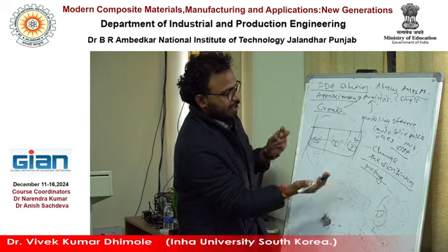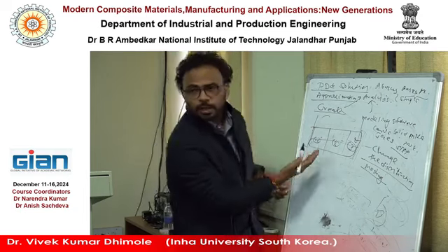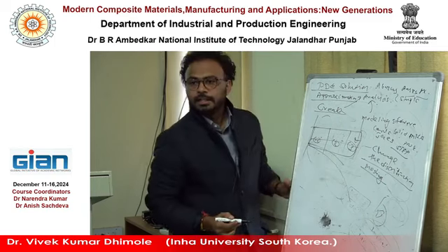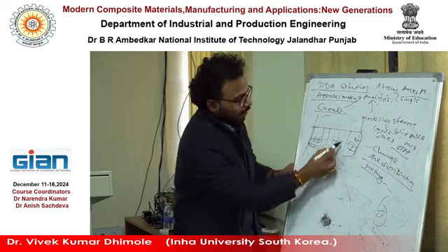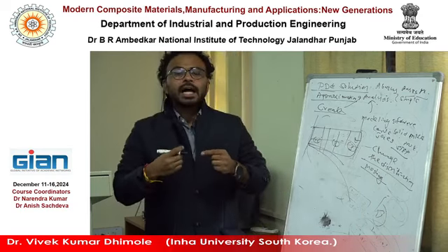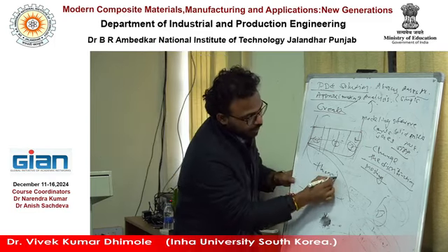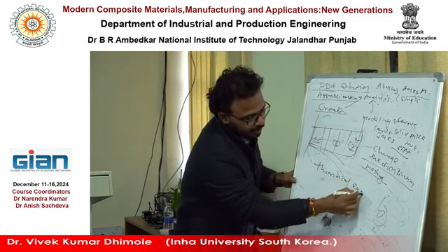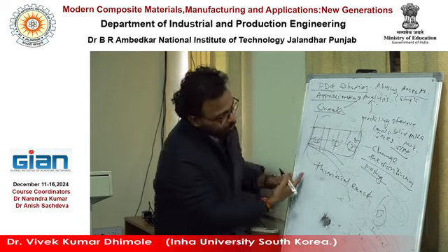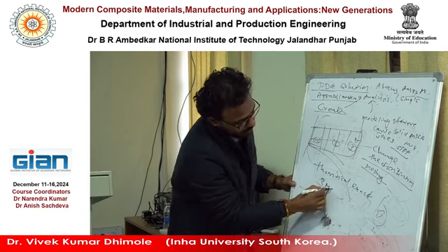It's just covering only 3 elemental equations, right? 1, 2, 3, and a summation of the shape functions and something like that. But this will not give you an accurate answer. Suppose the exact one is this, it will give you maybe this, right? Then you have to divide again. So you have to make the mesh sensitivity work up to the accuracy, right? You have a theoretical analysis, and you know the theoretical is exact. You have a formula for bending of a plate, cantilever, beam, right? So you have a result, suppose 3 megapascal stress is coming, right?